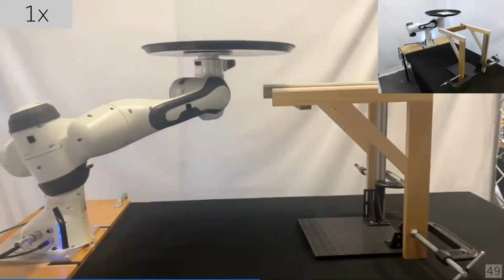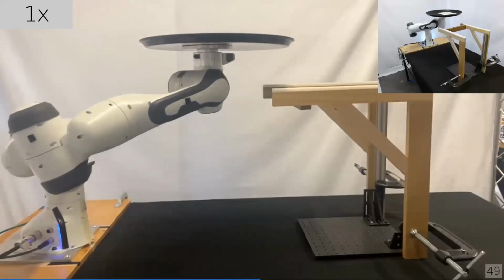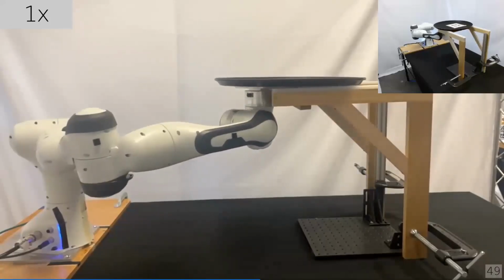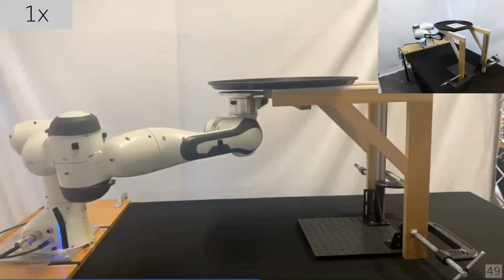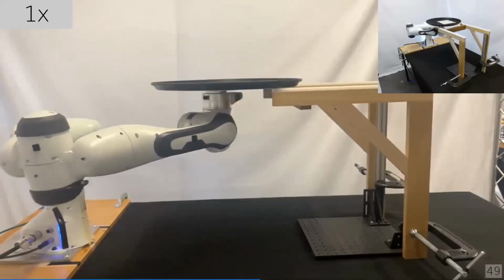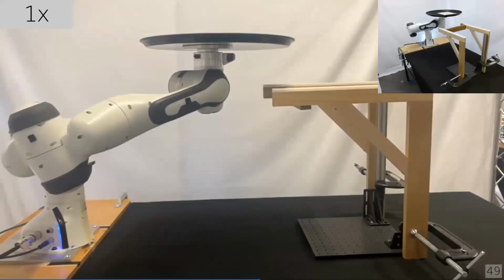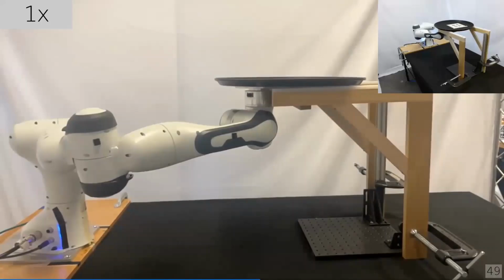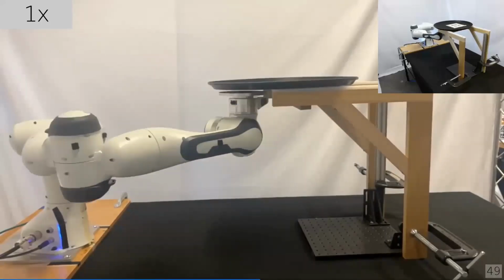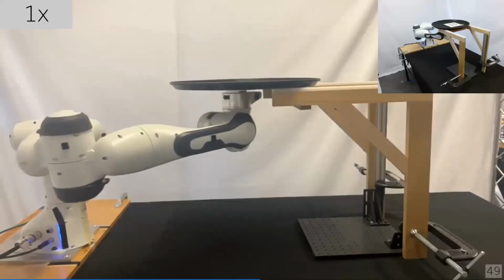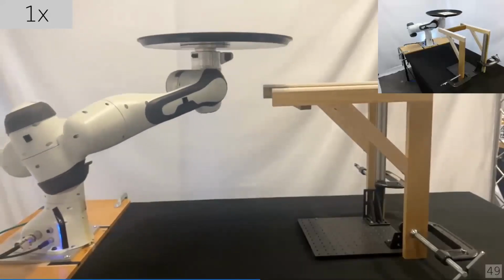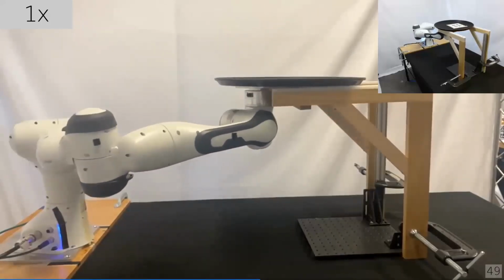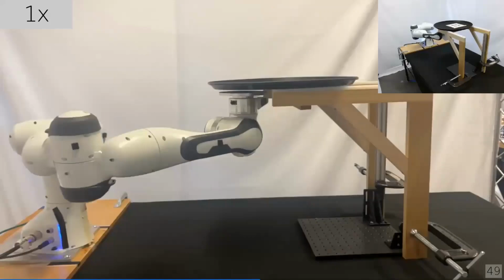This task embraces all the challenges of the dynamics of sliding that we discussed earlier. The system is underactuated, and due to the heavy reliance on sliding, we explore the full spectrum of contact modes, including sticking, sliding, as well as no contact. I just want to point out that it may be difficult to see, but there is actually a bar preventing the end effector from just directly grasping the object from below the center. And that's why we have to leverage sliding.